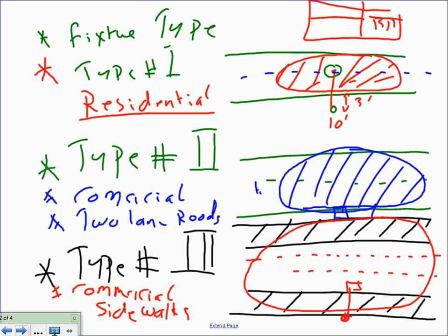So here's a couple of lanes here. You have a couple of lanes going on here, and you want a fixture right in here that can light the sidewalk, the street, and the other sidewalk on the other end. So it gives you more. It doesn't have 100% cutoff or 90% cutoff. So it gives you more forward distribution of the light. This one gives you sideways distribution, this way.